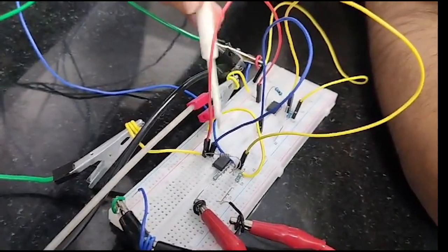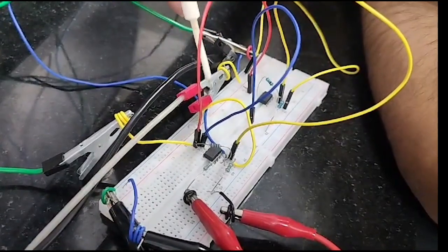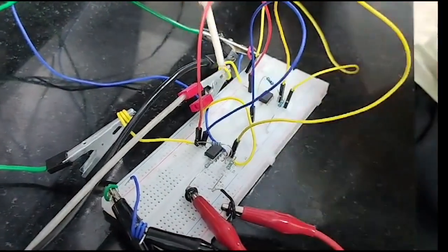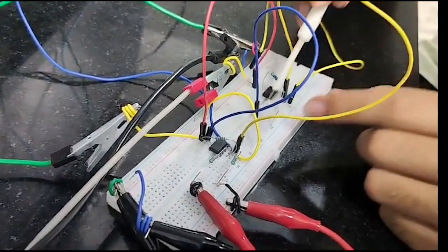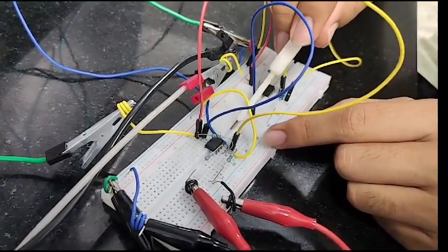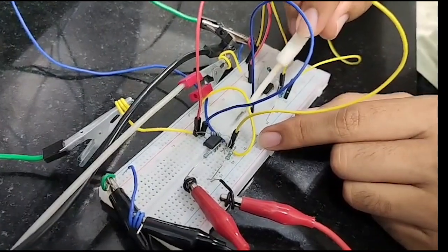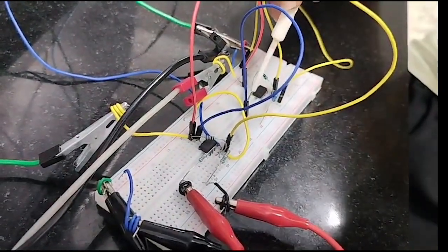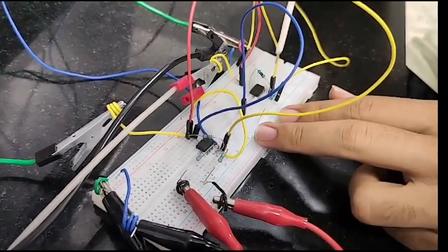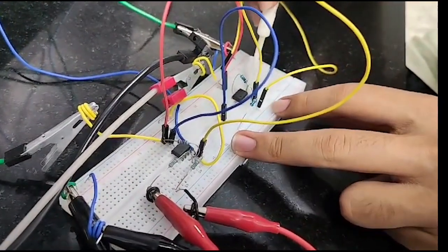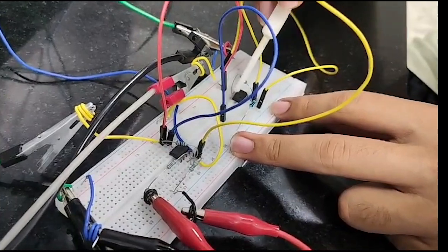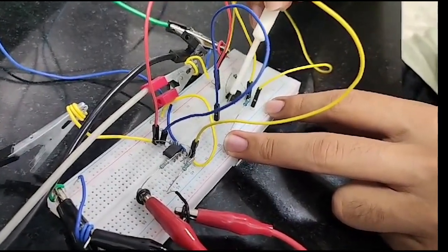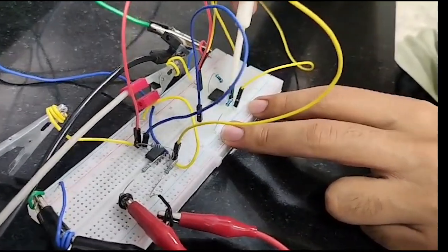And now the output of this is taken from the 6th pin, and is connected by the blue wire here. Here you can see, as it is an inverting amplifier, whatever output we are getting is inverted, so we need to invert once again to get the positive output. So in the second IC we have a buffer amplifier here. Now the output of the first amplifier is connected via blue wire, and now it is connected to the 1 kilo ohm resistor,